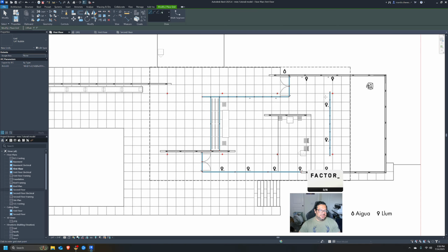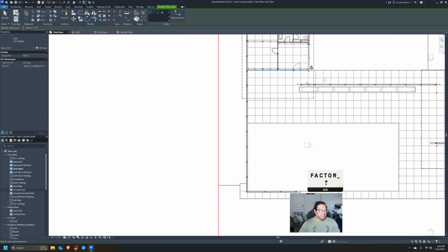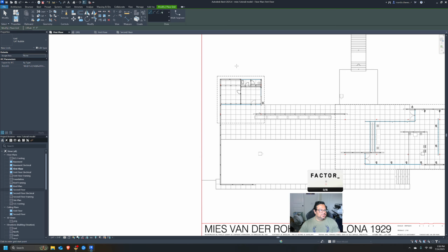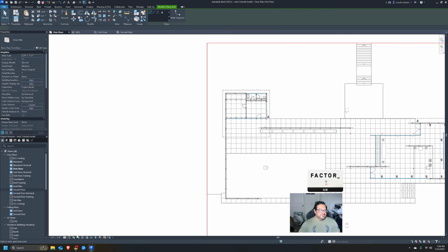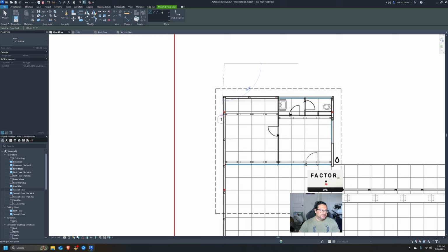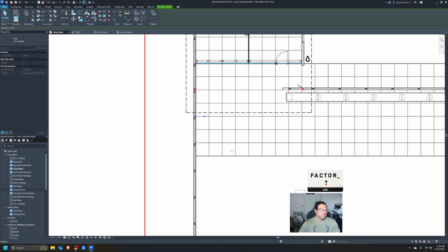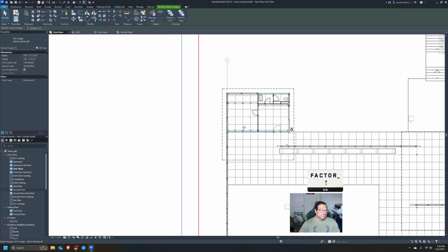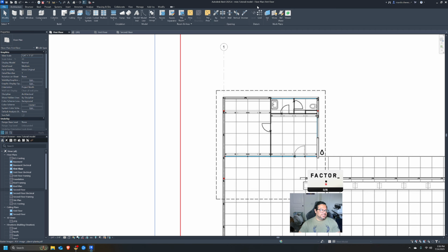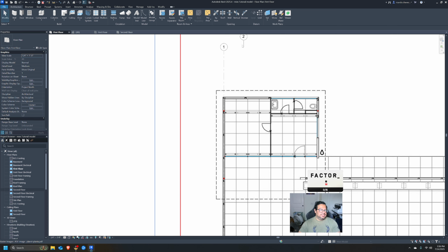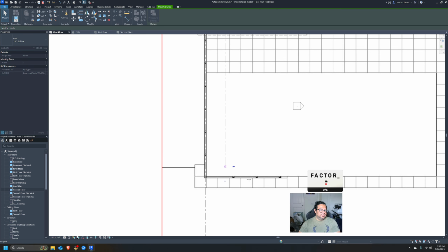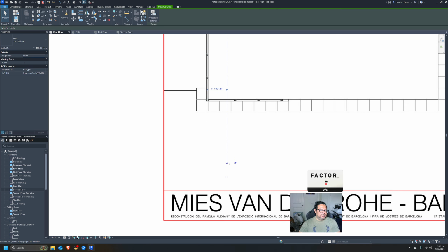Yeah, we'll just do those columns, and then we'll do the exterior, the edge of the slab. So we'll click Architecture, Grids, and we'll click anywhere, it doesn't matter, because we're going to copy them over. So I placed it there. The way I did it is you click grid, click once, and then you click twice. And that's how you place your grids. You can do either direction.